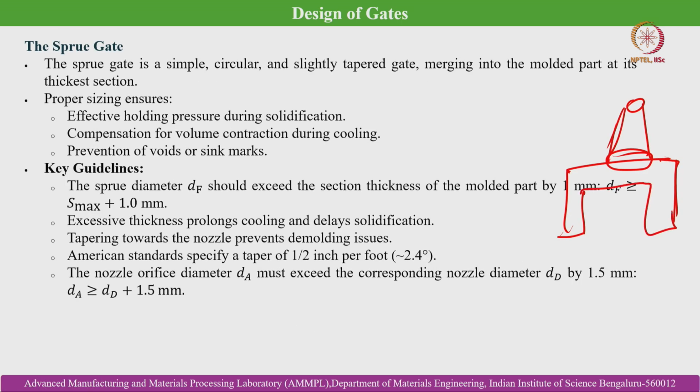Hence the proper sizing ensures effective holding pressure during solidification, compensation for volume contraction during cooling, and prevention of voids or sink marks.